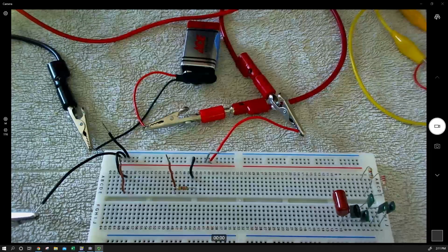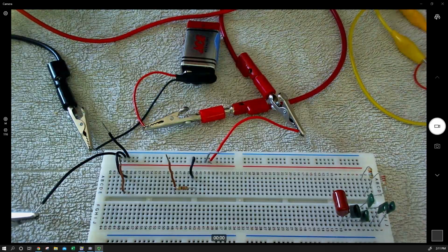As we saw with the high impedance circuit, one source in parallel, two sources in parallel, even though we knew those sources had a fairly high internal resistance, didn't really matter in the current that flowed through the load. And we hypothesized that was because the load resistance was dominating. So now let's see what happens when the load resistance isn't so big.